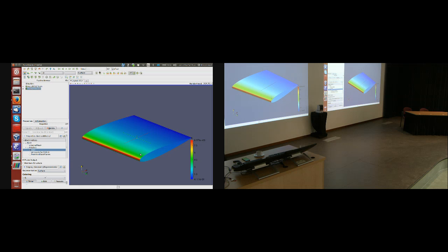Now this looks okay, but there is one parameter that I always want to check. You know what? Y plus, have you heard of Y plus? Okay, so we are using the K epsilon model with the wall functions. The dimensionless distance to the first cell must be calculated. Okay, it isn't here, it isn't on my list of fields. Okay, so if I click here, there is no choice of Y plus.